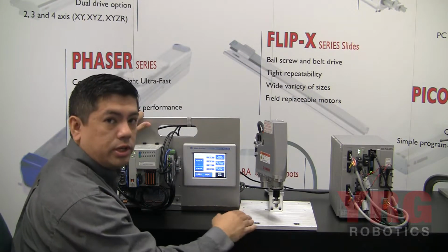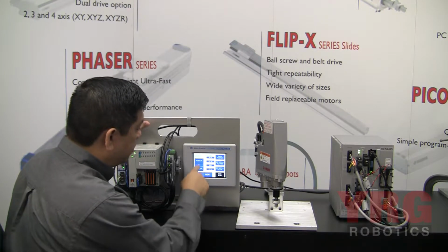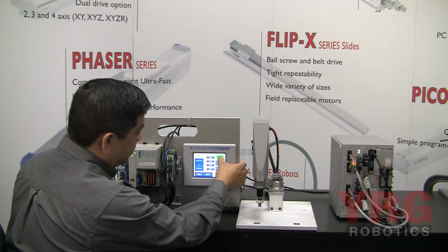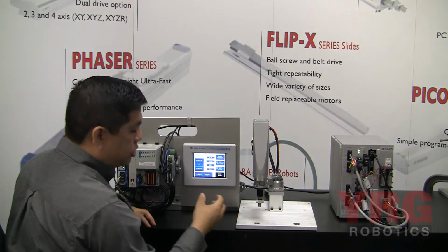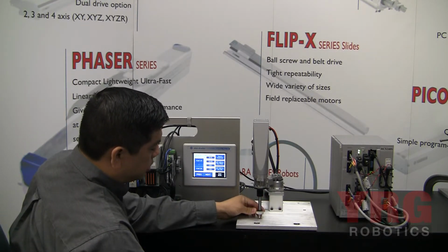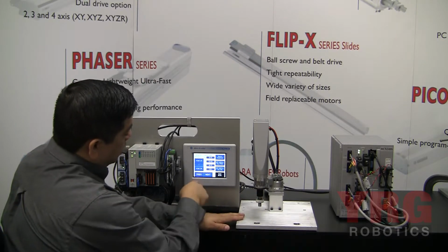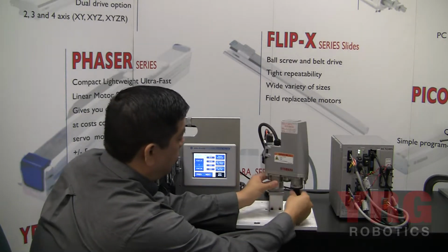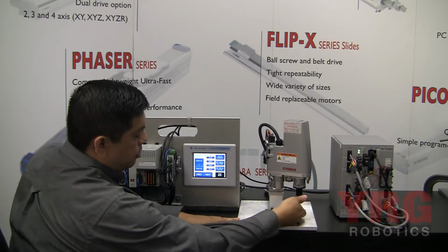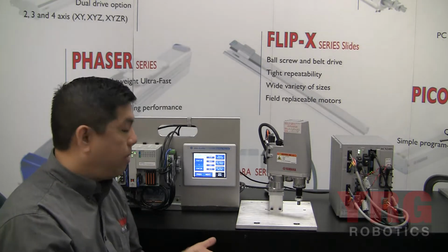Also, we can now grab the values from the robot and store them into registers in the PLC. So I'm going to teach a quick little pick and place program, 5 points, and I have a point register indexer here on the Panel View, and I'm going to store the home position into 0. I'll set the robot anywhere I want, and hit teach position. We're grabbing the values of the robot right now and storing those into the PLC. I'll index my position to number 1, and teach my first pick position. Then I'll raise the quill by hand, index to number 2 and hit teach. Then I'll move the robot to the down place position, which will become number 3, hit teach. Then I'll index up to 4, move the quill up, and hit teach. And there you go. I just taught 5 positions in probably less than 30 seconds.